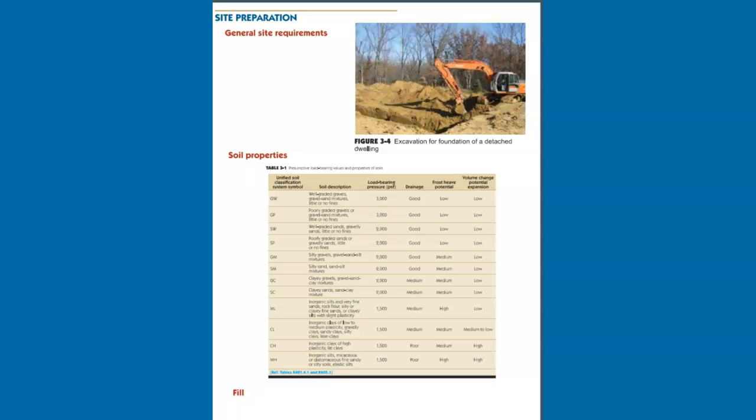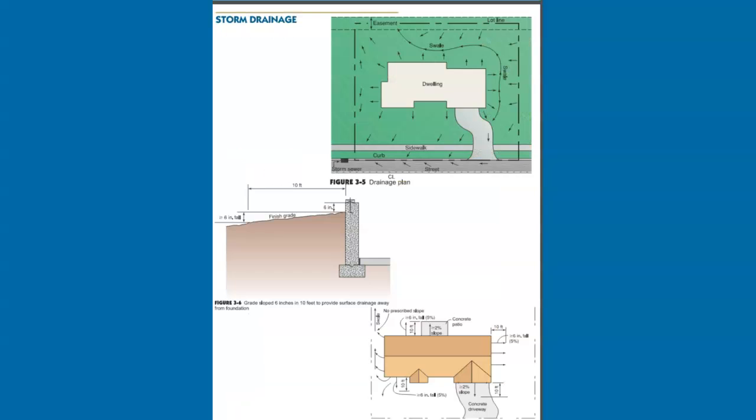Builders should also exercise care during the backfill of foundations with suitable fill materials to provide adequate drainage and to prevent damage to the foundation. Ref. R 106.1, R 401.2, storm drainage. The IRC prescribes methods to direct surface water away from the foundation to an approved location.